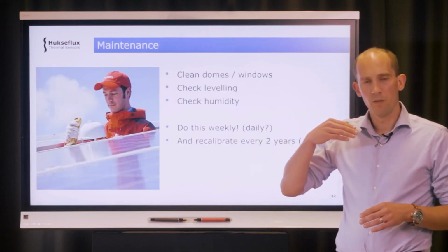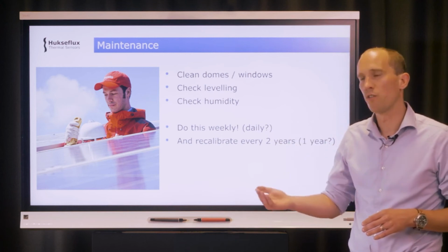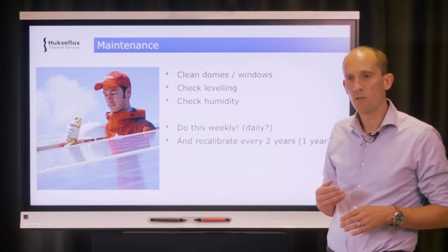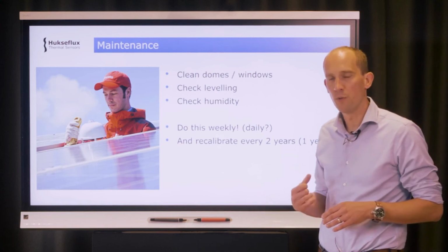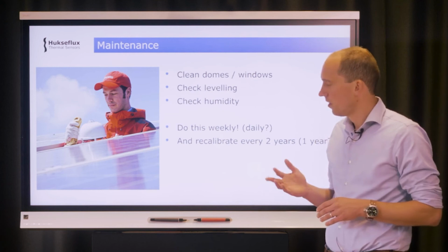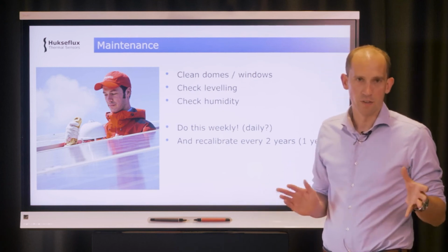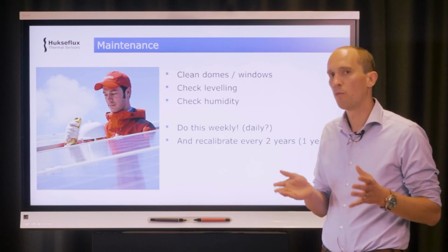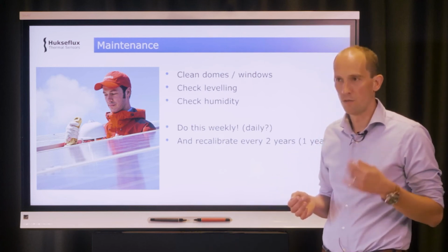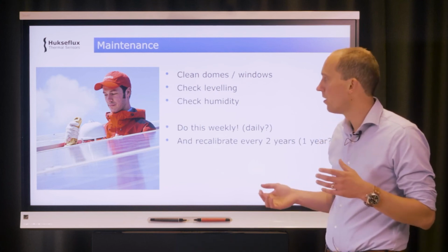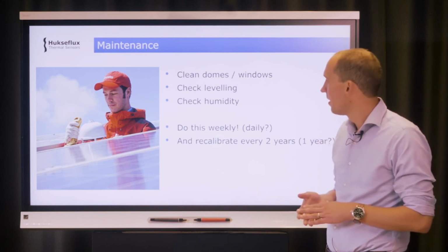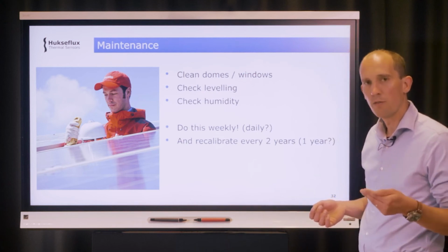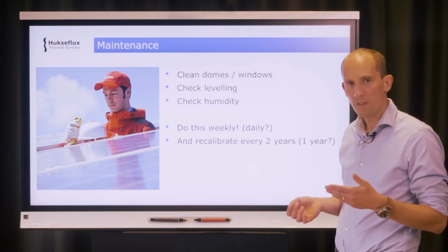Now finally, once you have your instruments installed and your data acquisition set up, you have to take care of your instruments. That's often called the concept of maintenance. How do you maintain your pyranometer or your pyrheliometer? The fundamental thing you have to do is to make sure that you keep your optics, your domes and your windows clean. Clean of dust, clean of water, and aside from that, you also have to check whether your instrument is still level and check the humidity inside your instrument.